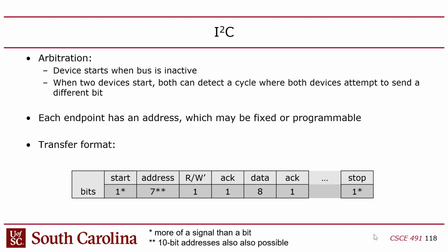Now there is a caveat to that though. There is this cool thing in I2C where if the slave decides that the master is running that clock a little too fast, or it needs some more time to think, it can actually do a technique called clock stretching, where, remember the open drain basically says that either side can pull down that signal.